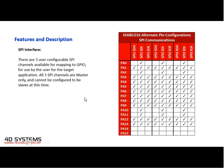So the 3 other SPI ports, as I have mentioned, are also mappable. That means you can assign SPI 0, SPI 1, 3 signals, for instance, to any of these GPIO pins. Similarly, you can do that as well with SPI 2 and SPI 3. Please note that all 3 SPI channels are master only. They cannot be configured as slaves at this time.